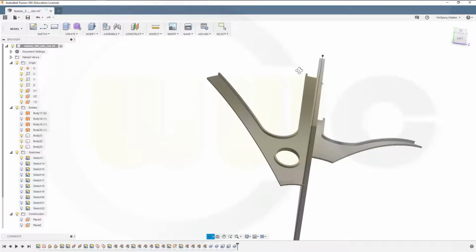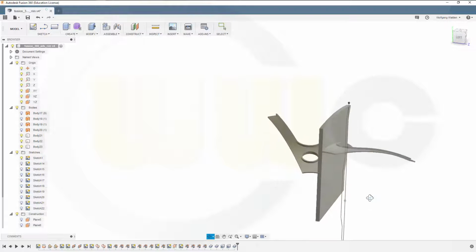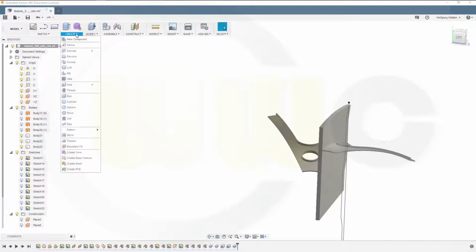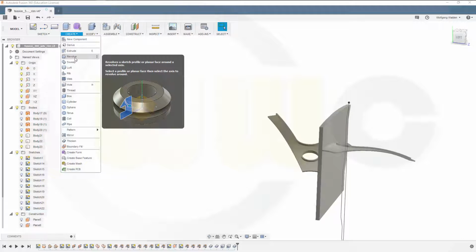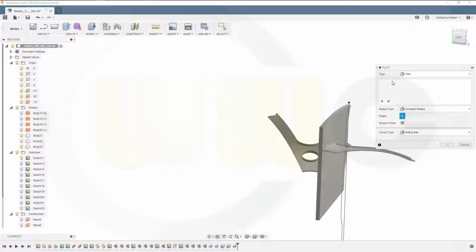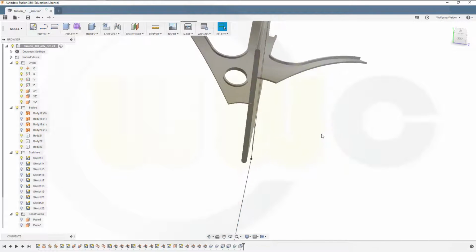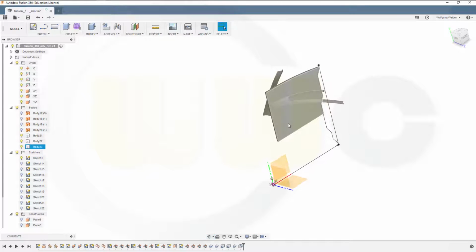Now I could add the fillets already. But first, yeah, so go for fillet, 3mm on this edge, that edge, this one, and the other one. Nice. Now a circular pattern with that body.